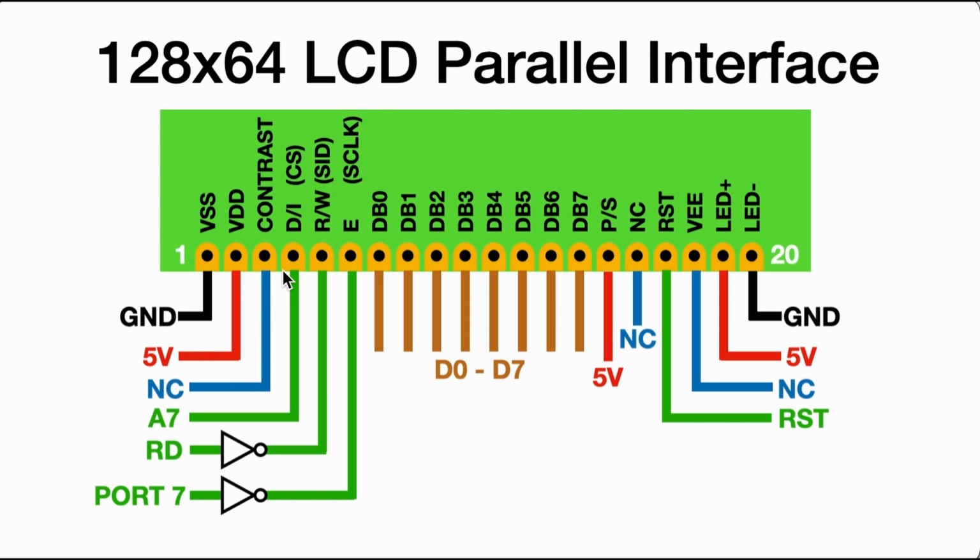And over here, this is interesting, contrast. Normally you would connect it to a 10K trim pot between ground and 5 volts to modify the contrast. It actually has got auto contrast, saves you one extra component. Okay, let's plug this into the Tech 1F computer now.